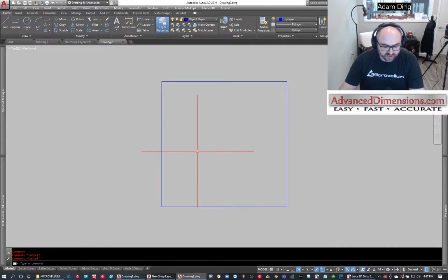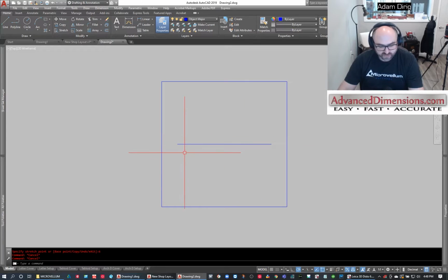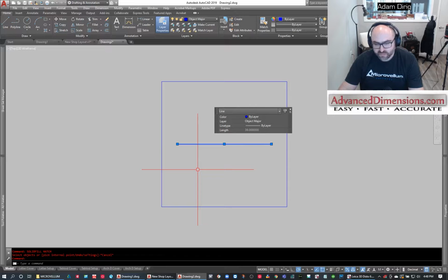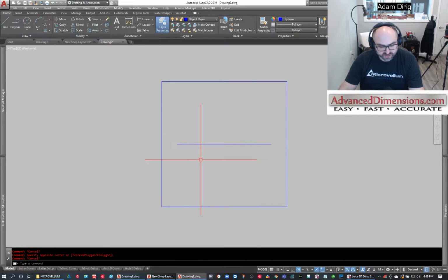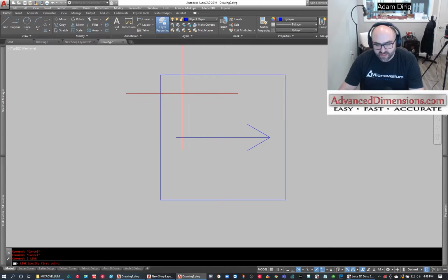So in this rectangle, I'm going to draw a couple of lines. Let's pull in about 6 inches, and we're going to draw a line that comes out, and we'll hold this back 6 inches. Let's just make sure that this is a good number. So it's 36 inches. Yep, that sounds about right. And let's put an arrow on here that is 10 inches, and we'll just mirror this. So I am literally just working in AutoCAD, doing some line spacing, nothing too crazy.